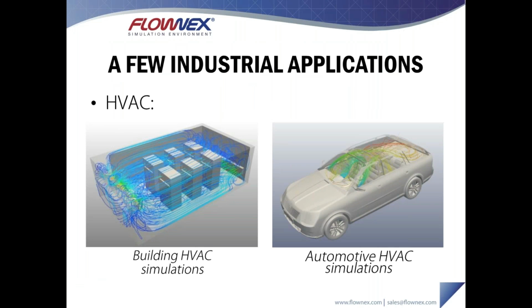Okay, so just to round it up, I'd like to talk about a few additional applications for this. So we already mentioned that we can look at HVAC from a building point of view. This can also be extended into the automotive sector, where we start looking at modeling the HVAC systems for traditional automobiles. So here we would model the refrigeration or the cooling system, as well as the vents for the car inside of Flownex, and then have the airflow and the radiant heat sources inside of the cabin be solved using something like Fluent, for example.